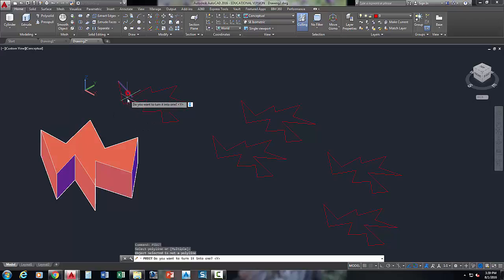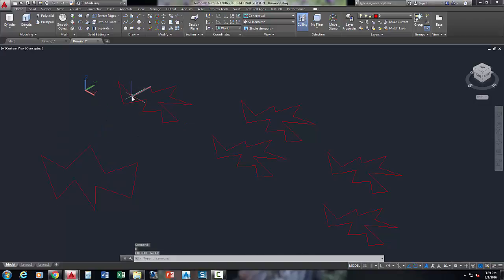You select a line, and then it says, hey, that's not a polyline. Do you want to make it one? Yes. And then you had the option to join, and you could join this whole thing together as one long continuous polyline. AutoCAD, a couple of releases ago, came out with this option, though. If you go to modify, you've probably seen this before, that join command. Join does that, and it skips over that p-edit. Click the line, then make it a polyline.